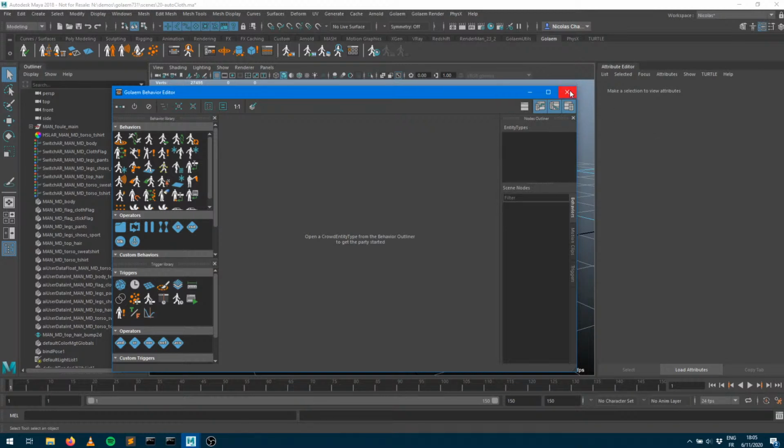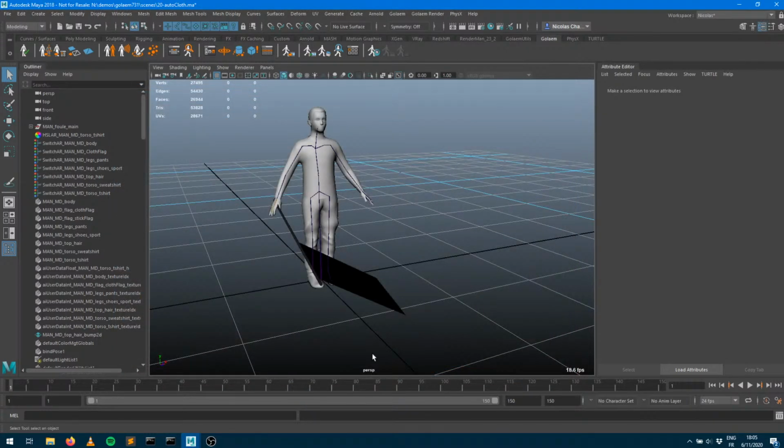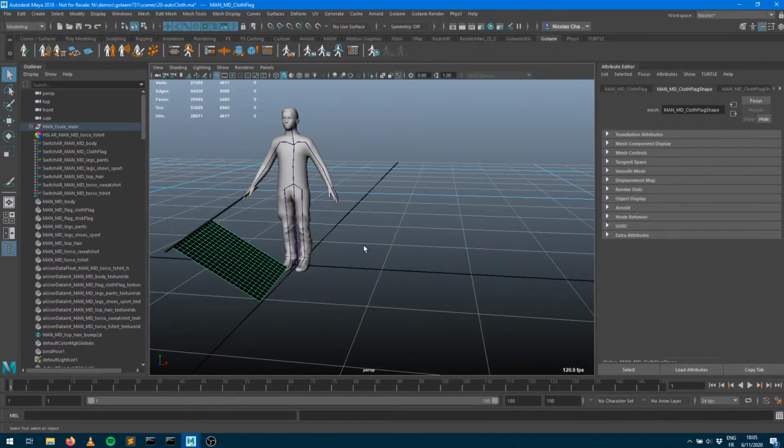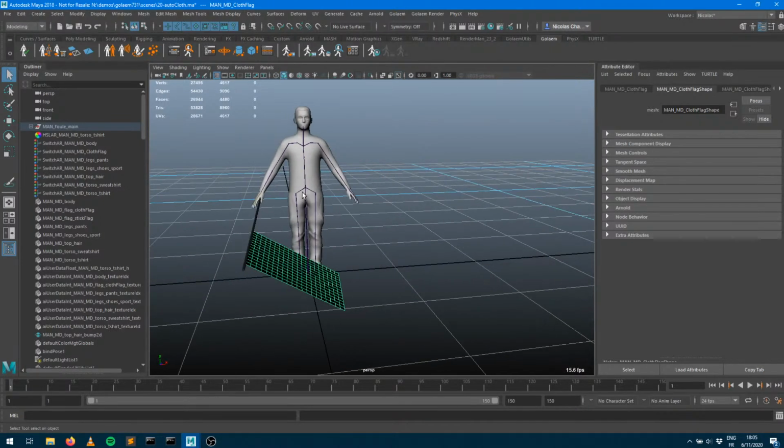Cloth simulation means that we're going to make a simulation based on the geometry of characters. Within Golem, what we used to do is always control the skeletons and inject some postures, and what's written within the cache is bone positions and orientations. Here, the cloth is going to be different. We're going to write actual vertex deformations, so that happens at the vertex level.